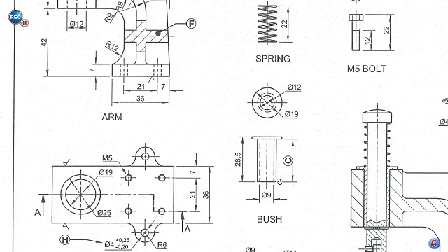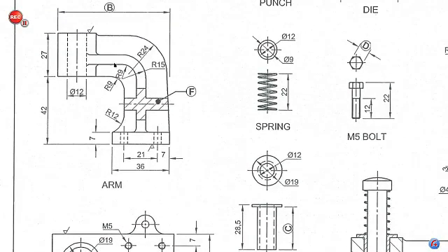If you look at C, C is the distance from this bottom section of the bush until the bottom part of the head. You will see that the bottom to the top part is 28.5. So that bush fits into this space over here, and you will see that the bottom of the bush fits from there until this bottom part of the arm. And if you scroll over to the arm, you're going to find that the arm from there to there is going to be 27, which is the perfect fit for the bush. So the answer to that is 27.